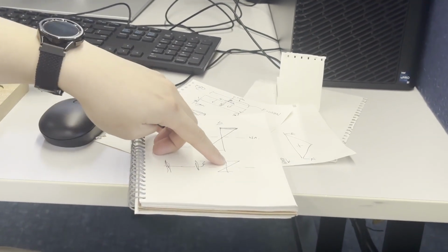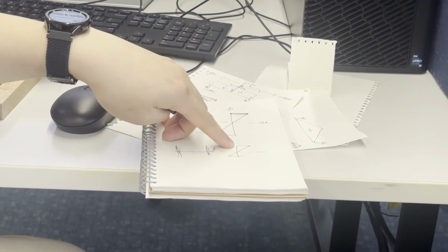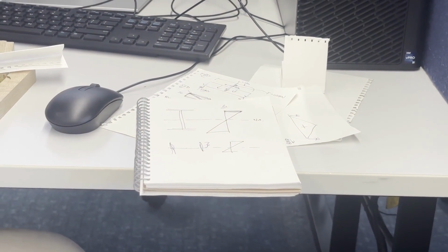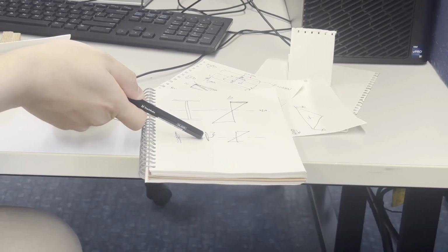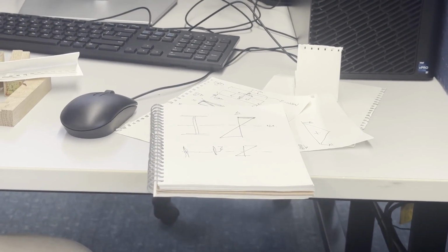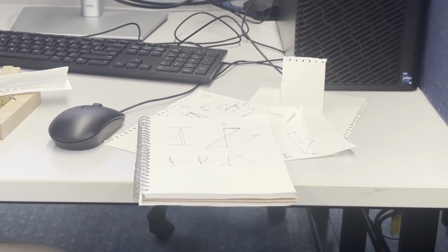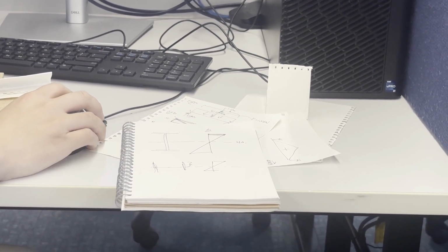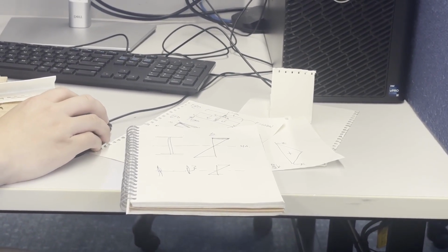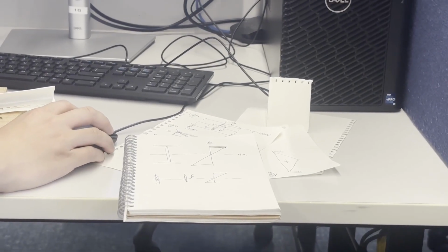This flange here is taking a varying amount of stress. Does that make sense? Because it's taking the most stress here and then less towards the neutral axis in bending. And that's even on both sides of the flanges? Yep. But you would consider that flange and that flange the same when you're evaluating its plastic limit and yield limit on this table.